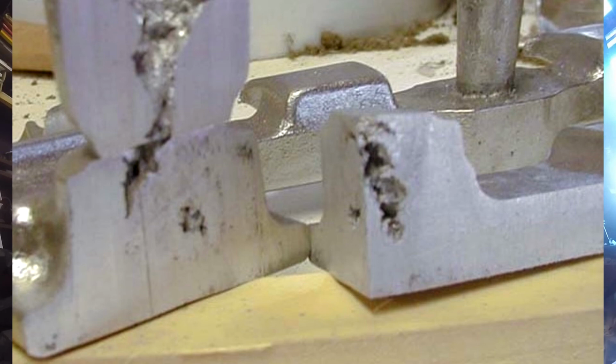The problem here is that the neck was narrow enough that it restricted the flow of the molten metal and froze up, and then the molten metal that was left over inside the casting was used up, and you had your gap formed inside there, and then the molten metal inside the riser was used up, and it looks like the piping almost went all the way to the base of the riser.